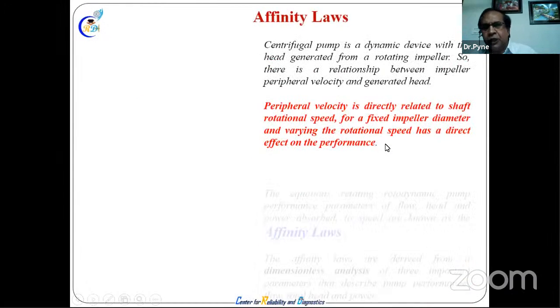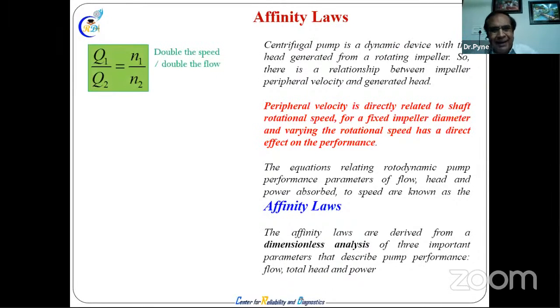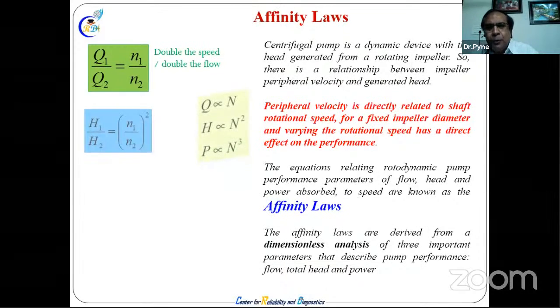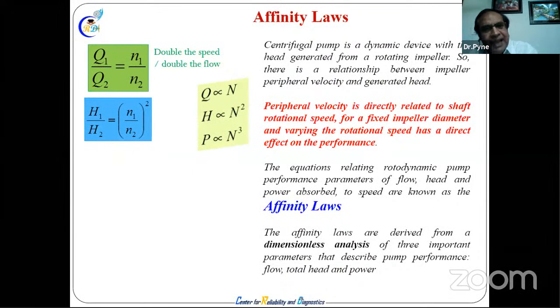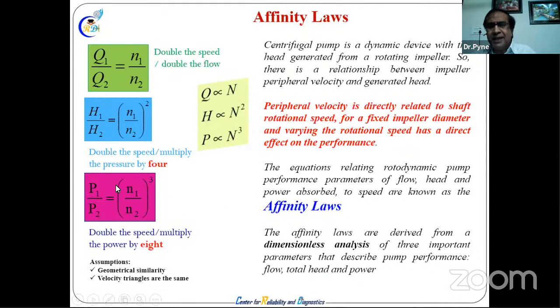In the affinity laws, affinity means how much relationship there is between the parameters. We are trying to explain, at unit level, what our flow, head, and power requirement will be when you change the RPM. So whatever you think in the VFD, you cannot do whatever you feel like. This is controlled by this formula. RPM can be changed, but with a little RPM change, your power requirement will change greatly. Can you see this here? The formula is cubic.